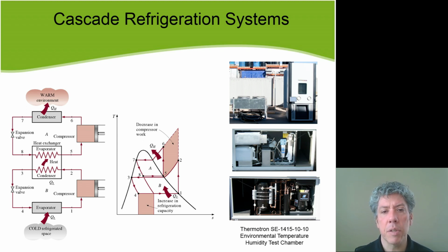Go from state 1 to state 2, and then up the dotted line to that very tall peak, and then down the dotted line to state 6, on down at constant pressure to state 7, then on to state 8, and then following the line that's not marked, that would just continue the line from state 7 to state 8, down, and then over back to state 1. That would be a simple vapor compression refrigeration cycle, and it wouldn't be all that efficient because the temperature difference between state 1 and that high peak is so large.